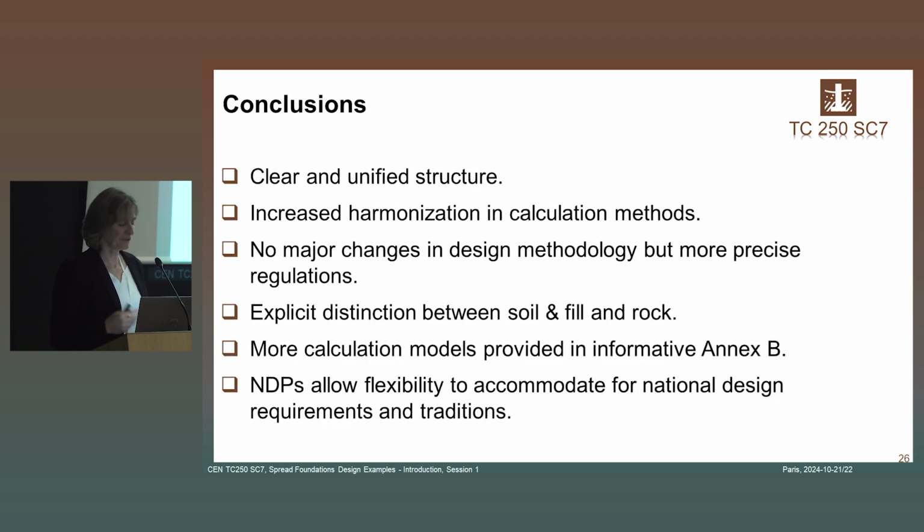Now, in the end, we have, I think, a clearer and unified structure. You know exactly where you find what. There's increased harmonization in regard to the calculation methods, and there are a lot more calculation methods now in the annex. There's a clear distinction between soil, fill, and rock. And there are no major changes in the design methodology, at least for spread foundations. So you design it in the way you're used to, but the verification procedure is different now because you have to use the different codes, and also there's a different format with the verification cases and so on. So this is what you need to get used to.